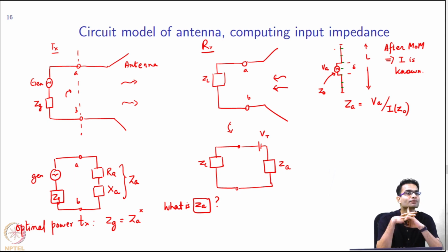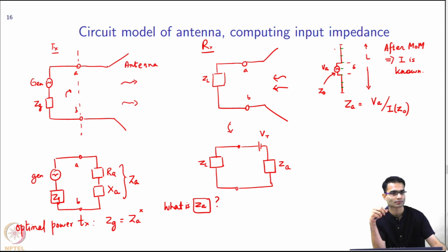You cannot match the free space impedance. Yeah, you can't match that. I mean, you have your circuit impedance as, let's say, 50 ohms, 75 ohms, and then you have to match it over there. You can't match free space. Not all the radiation is going to go into free space. You live with that. Okay. So the procedure is clear. How do I calculate the input impedance?